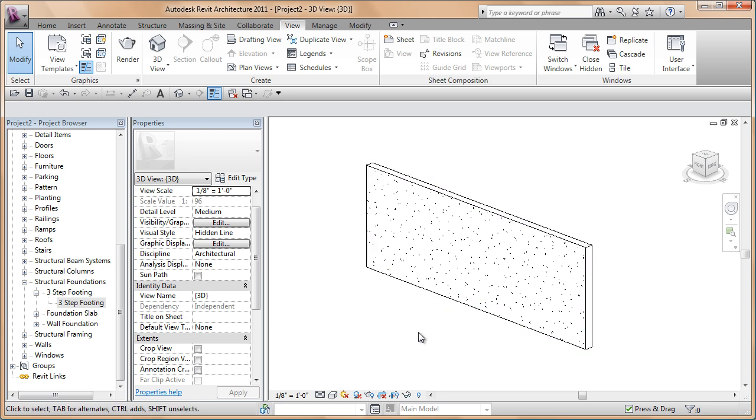So I just have a piece of wall here that is 8 inches and it's concrete. I want to drop that wall down and create a step footing, basically. Revit out of the box really doesn't do a very good job at allowing you to do that, and I've done it with in-place families and finally decided to just create an actual RFA family file and insert it and use some aligning tools to quickly get that. So this has 3 steps in this footing.